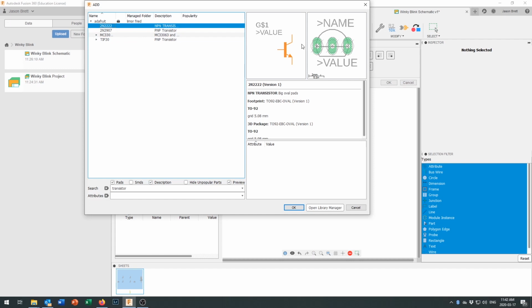Now, a lot of transistors will look exactly the same. So all the bipolar junction transistors that we use, BJTs, as opposed to MOSFETs, have a particular type of chemistry and design inside the transistor that makes them work. So a 2222 and a 3904 in a circuit like this are going to function very close to identically.